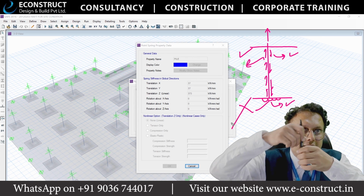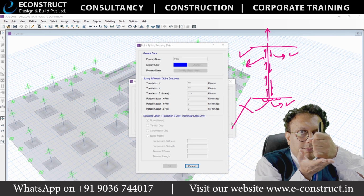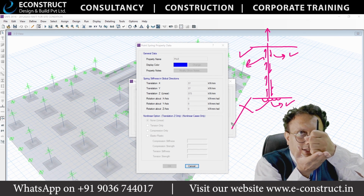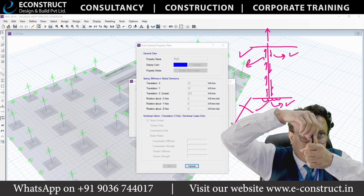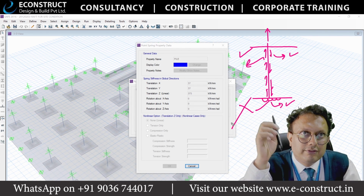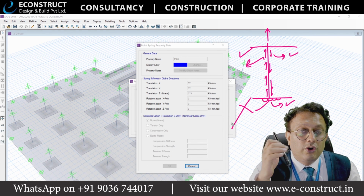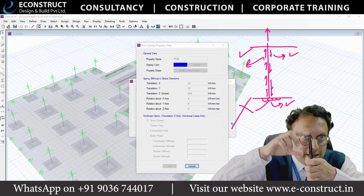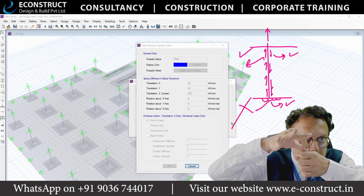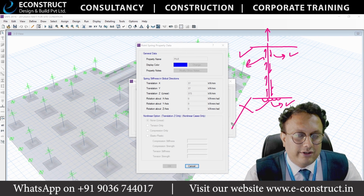Do you agree? If the pile is going down, the bottom surface will say, okay, I am resisting it, but if the pile is coming up, the bottom portion will say, if you want to go, go to hell. Do you agree? It's a non-linear analysis. So the spring constant of the pile when it comes to compression is different, but when it comes to tension, it's totally different.